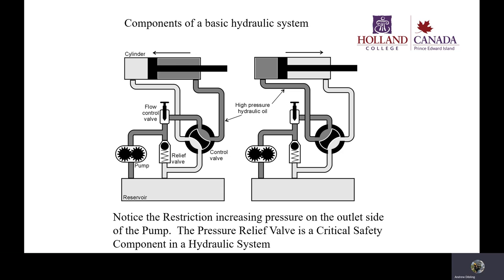That's kind of what it's there for. It's not there for, as I mentioned before, everyday running conditions. There are other ways to regulate pressure than just using your relief valve to do that with. It's more like a fuse or a circuit breaker. Okay, from the flow, you have this control valve, and this is a rotary control valve. So we're looking at the darker fluid being the high pressure fluid, and it will come into the front of this cylinder and will retract it.